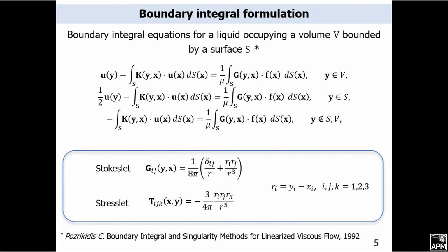Consequently, it is not necessary to discretize the entire three-dimensional region. Only the surface of the elements is covered by the triangular grid. Application of the boundary element method allowed us to reduce the dimensionality of the problem by 1 because all calculations are related only to the boundary of the considered objects. The boundary integral equations of the problem on the flow of a viscous fluid occupying a certain volume bounded by the surface S are written as follows on this slide.